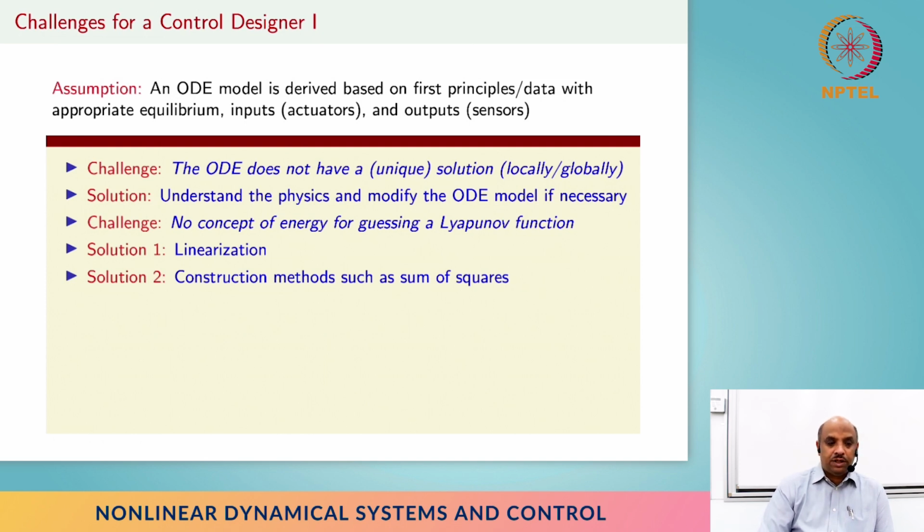Linearization is a nice method. It's a local method. If you recall, basically it simply approximates the nonlinear system to a local system. And it has its limitations, because if there is a system that has essential nonlinearity, some kind of limit cycle behavior, or something like a cubic nonlinearity to start with, and you don't want to throw away that particular cubic nonlinearity, then we'll end up with difficulty.